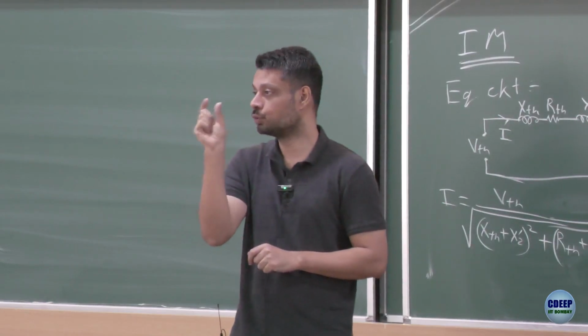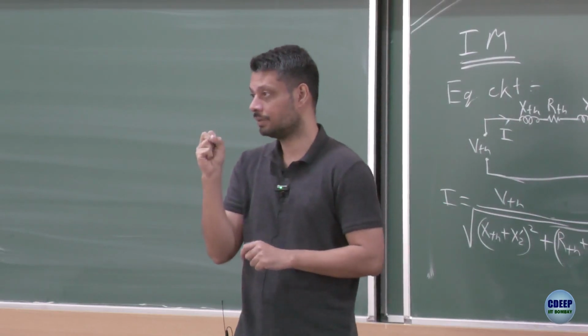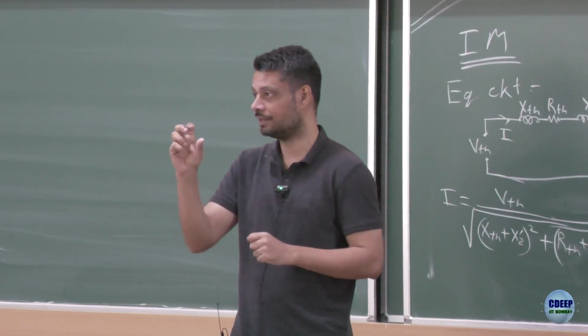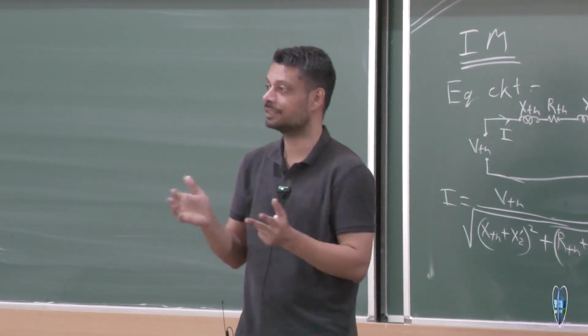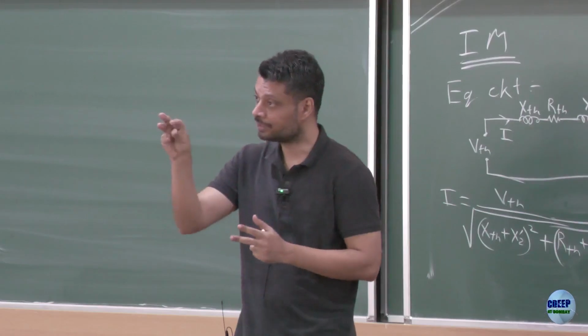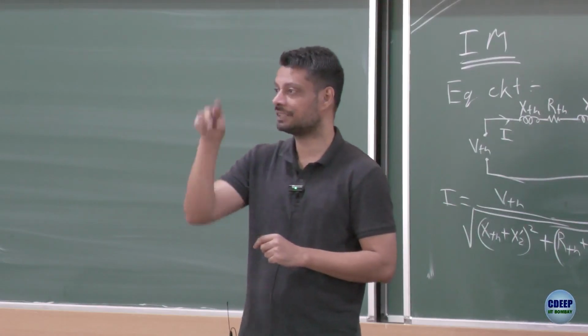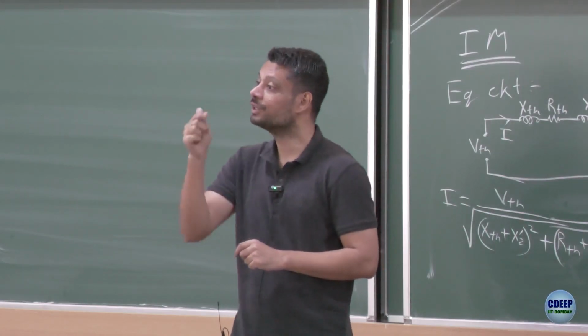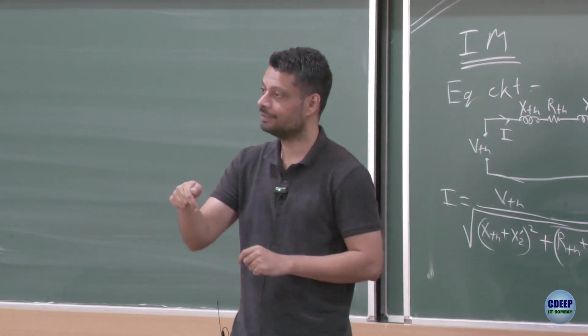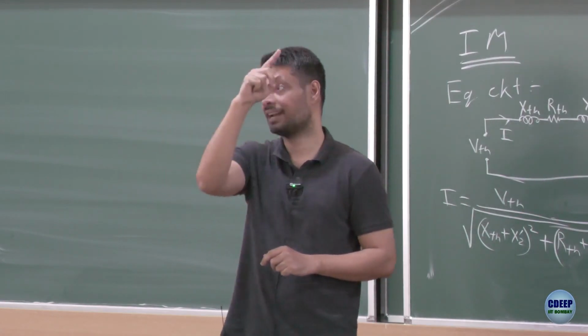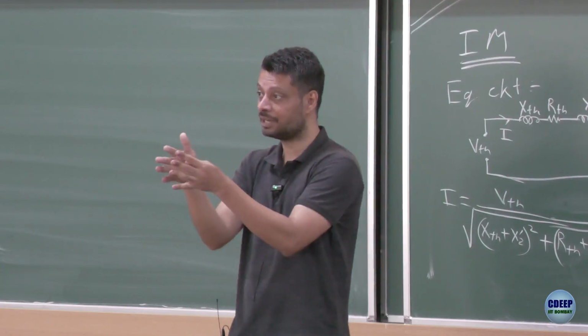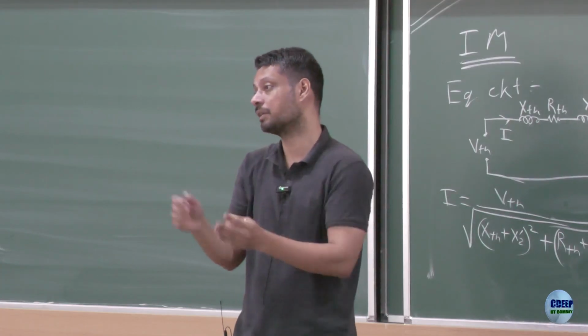The one which occupies 2 switches, if you open it and see inside, you see capacitors inside the regulator also, and those capacitors act as a voltage divider. So even those capacitors degrade, and therefore you change the fan regulator capacitor, but you didn't change the regulator. If you buy a new regulator, it will again work fine.